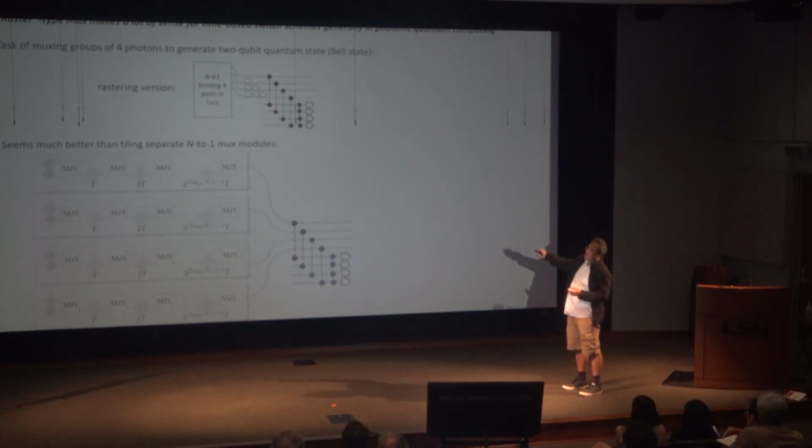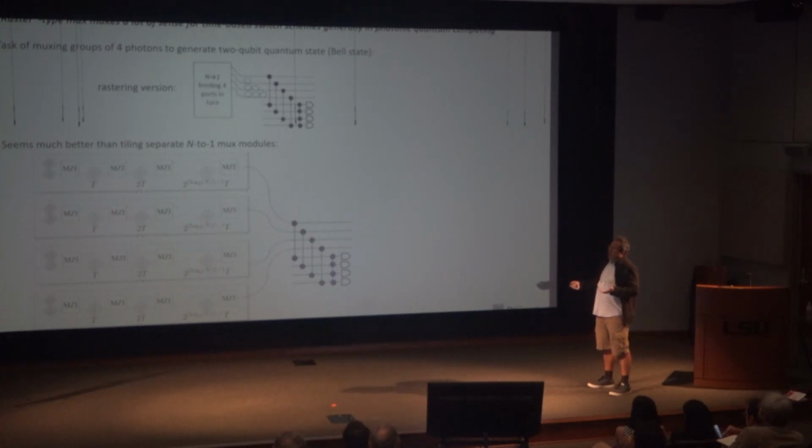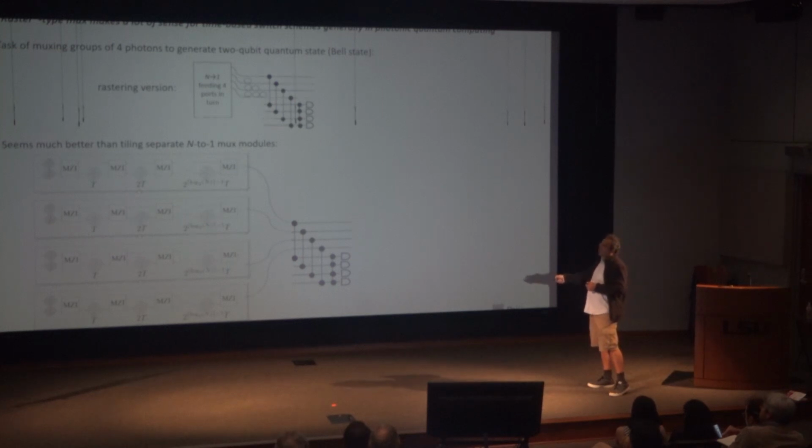A simpler thing to do is just to take an n-to-1 switch network and in turn feed 4 different outputs and compensate the delays at the output, which is something that comes for free. So time multiplexing like this needs only one layer of switching. It doesn't need 2+ layers of switching, which is what the default is.